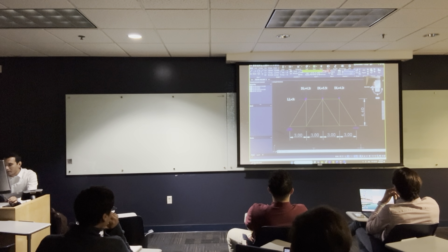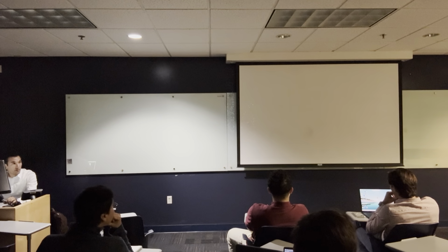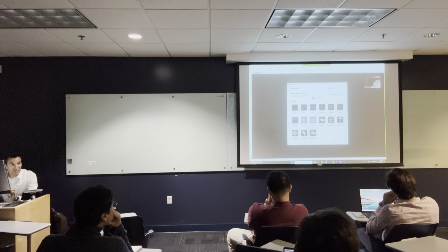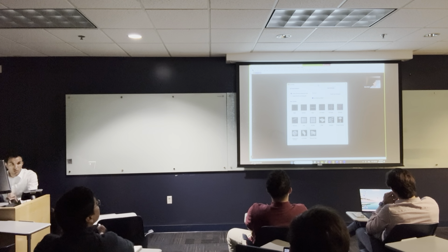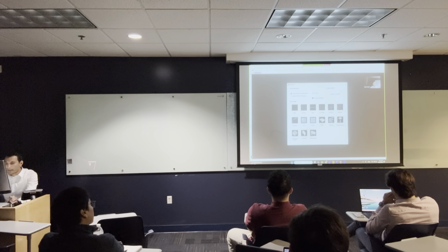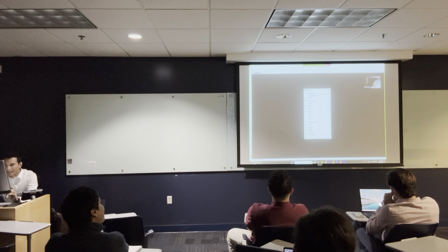So I'm going to go to SAP 2000 and pick that my units are ton and meter. If your units are kips and inch or kips and feet, you use kips and inch or feet. The first thing that you have to do in any structure analysis software is to pick the units. So I'm picking ton-force, meter, and I'm going to tell SAP 2000, hey, I'm going to start with grids, and I want you to help me with that.